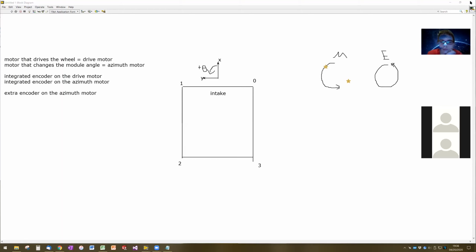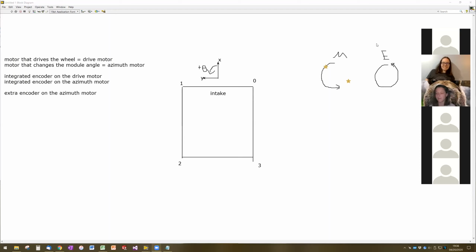Okay, so there's something to do with the direct DIO. Those ones are either 0 or 5 volts, but with the analog ones, if they touch stuff, they mess up, and it's not just 0 or 5, it's everything in between. So if it brushes up against stuff, it doesn't have a happy time. Yeah, that's exactly right. So let me draw that for you guys.